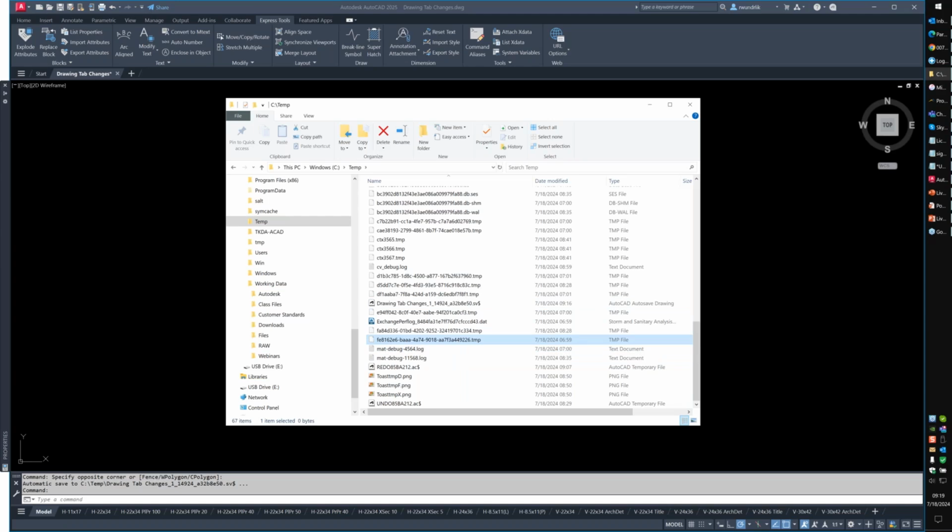Well, that's a very good point. So Corey, you probably have a different situation. You have a configuration problem. So what AC Core Console is, for those of you that don't know, is headless, modeless, licenseless AutoCAD. Basically, AC Core Console allows programmers like myself to do things in the AutoCAD environment. I can run scripts, Lisp, things like that without actually opening AutoCAD to a user interface. That's typically what AC Core Console is doing.